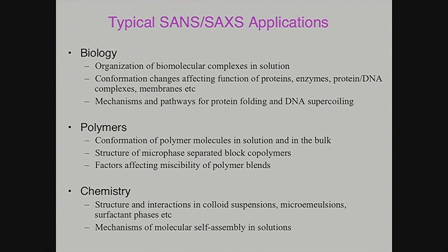Then in principle you can see which one is the chain you think about. So that was first done with neutrons, with a polymer. They put a few deuterated polymer chains into a melt of hydrogenated chains of the same polymer. That turned out to be a bad thing to do because, as I've told you before, hydrogen has a huge incoherent scattering cross-section, which is background.